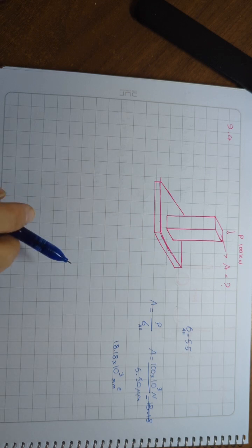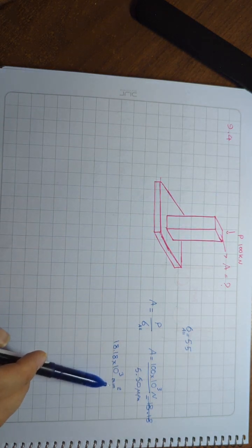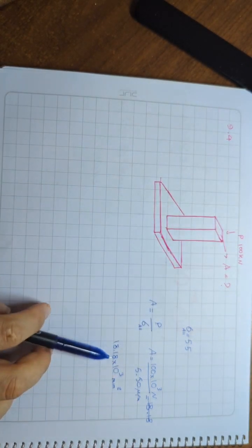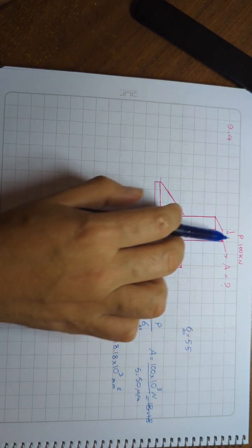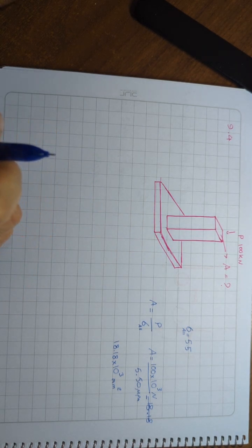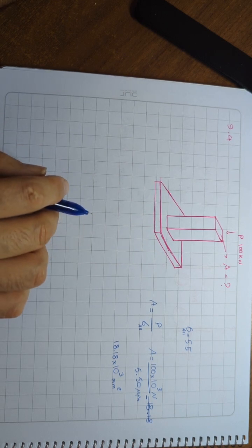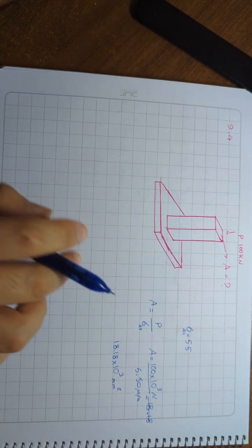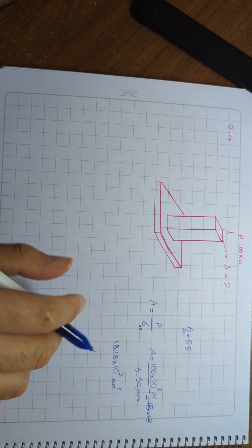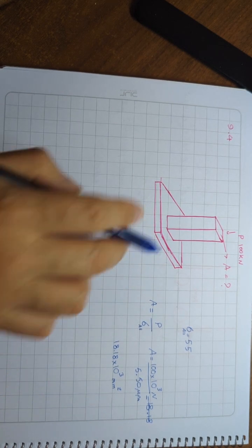This means that if this cross-section area is this big, it can endure this much load. If the cross-section is smaller than this, the structure is going to break. And from Appendix E, Table E2, a nominal 150 millimeter by 150 millimeter square timber member has a cross-section area of 19.6 times 10 to the power of 3 millimeter square, based on the dressed dimension of 140 millimeter by 140 millimeter. Therefore, we select a 150 millimeter by 150 millimeter post for this.